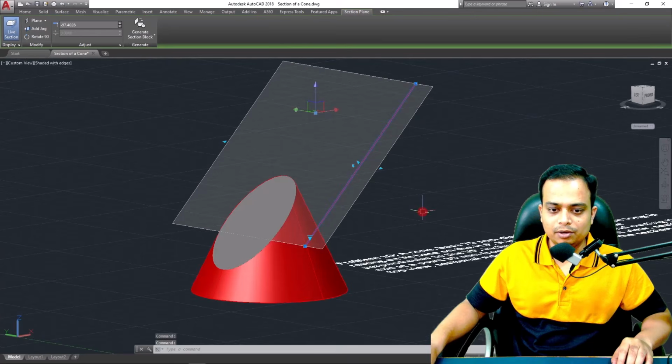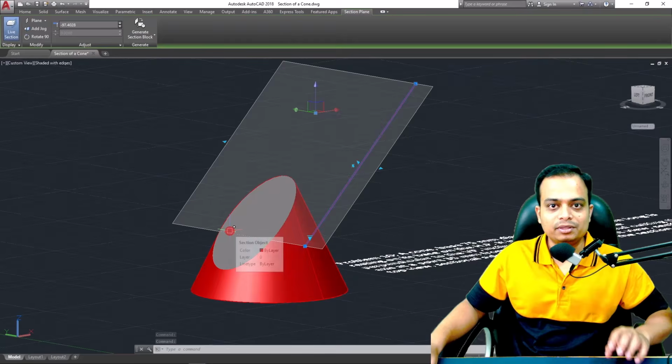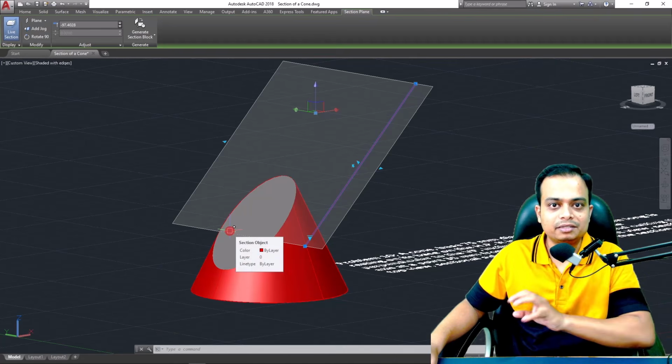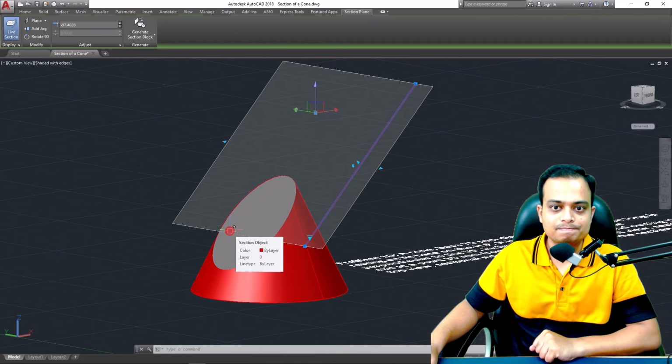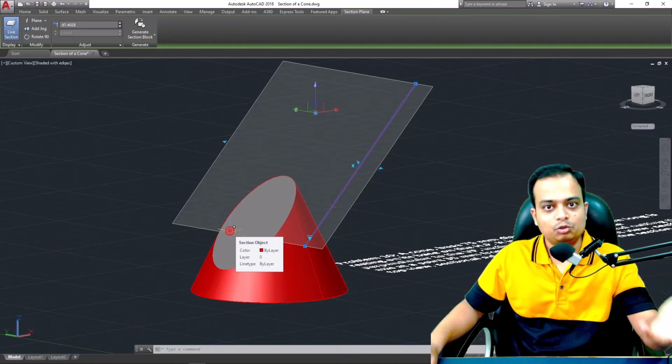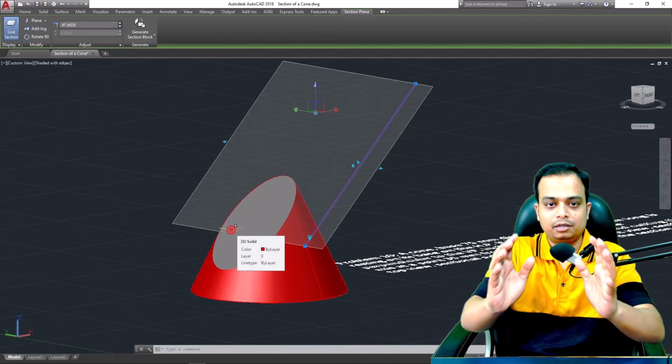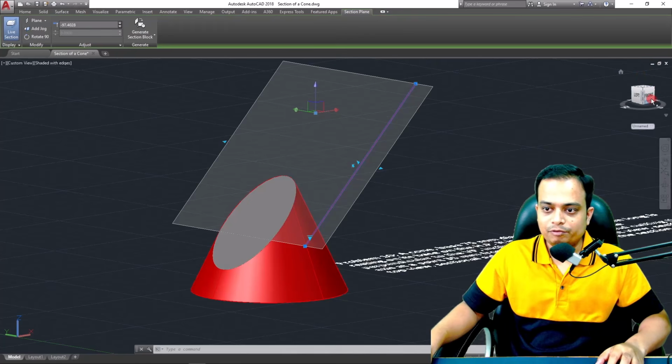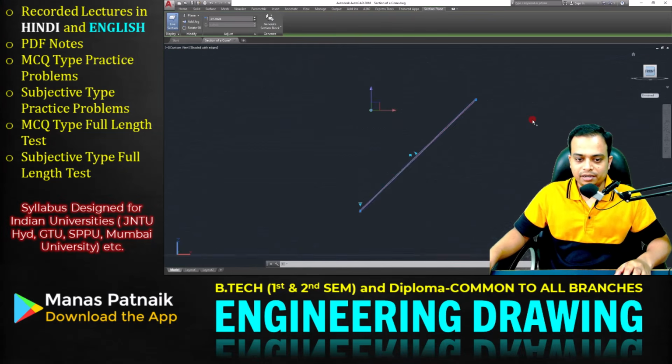See how it looks, sir. The section is in the form of an ellipse. So in the sectional top view there will be an ellipse, in the sectional side view there will also be an ellipse, and the true shape obviously has to be an ellipse. Okay, the true shape really. Now if you want to take a look at it from the front, here it is.